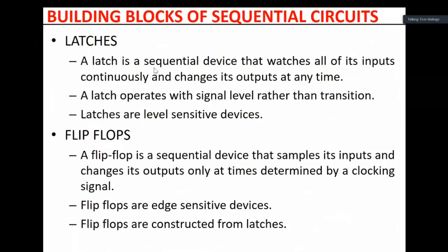That is an asynchronous sequential circuit. It doesn't have a clock. It operates with signal levels rather than transitions. They are level sensitive. And then what is the difference between latches and flip-flops? Flip-flops are clocked. The output is only allowed to respond at a particular edge of the clock. They are edge sensitive. Actually, flip-flops are made from latches.